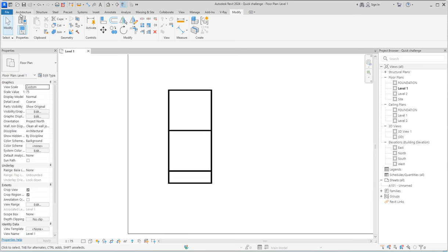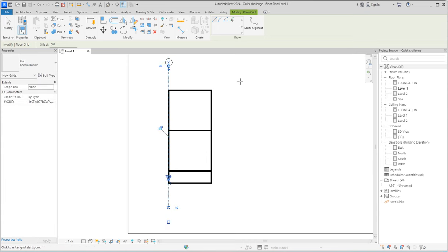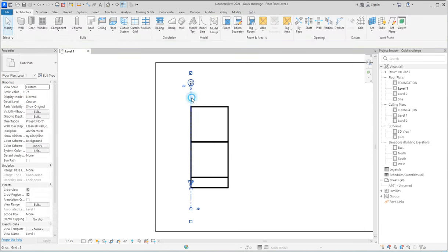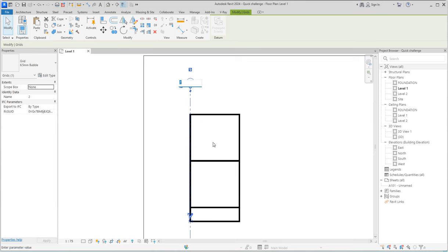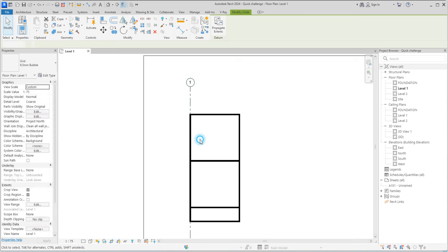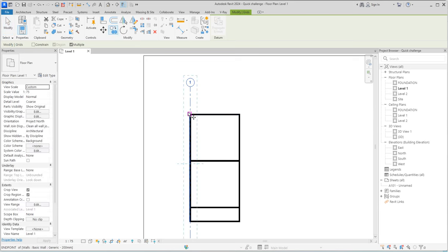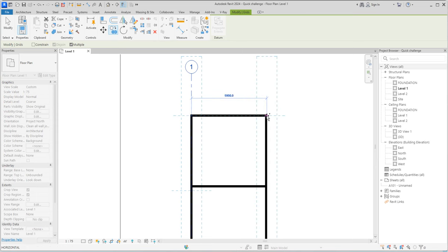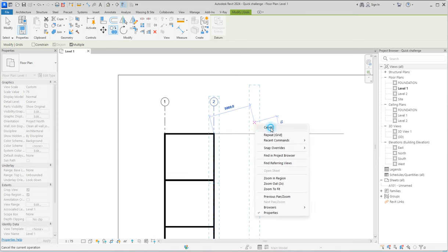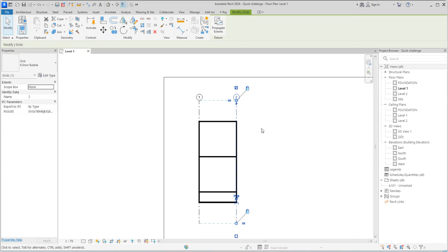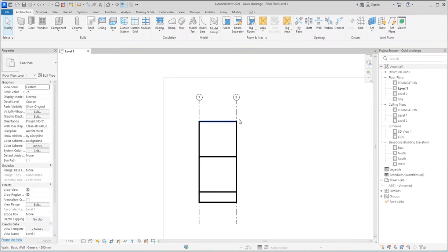So you come to Architecture and select Grid, pasting your grid line on this level. The reason why you are having grid lines is so that your drawing will have its own pattern. When you have created one, you'll be able to replicate it on a grid system to every other apartment. You put the second grid by copying this, or you click on create. The moment you click on copy, it's going to put that and you rename it straight up. So that is the second grid. In this place, you are going to have as many grids as possible, but we are going to get there by replicating the grid, including the building.